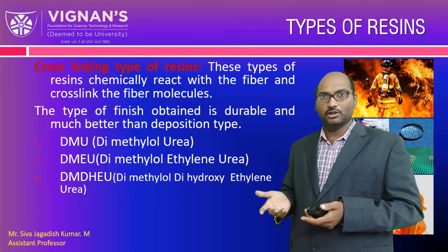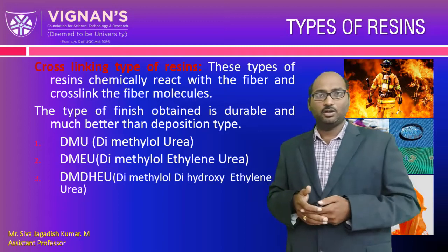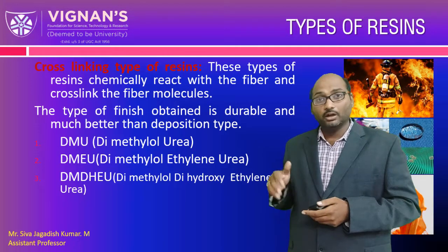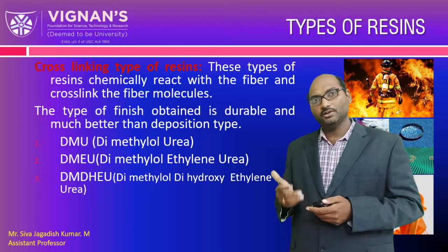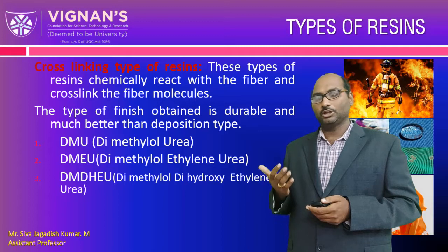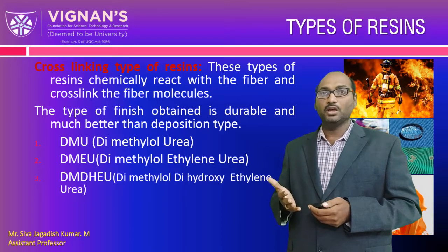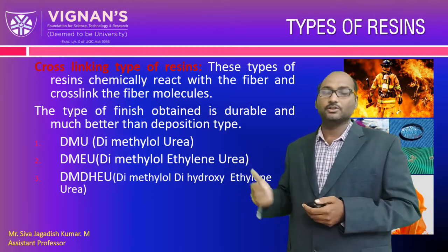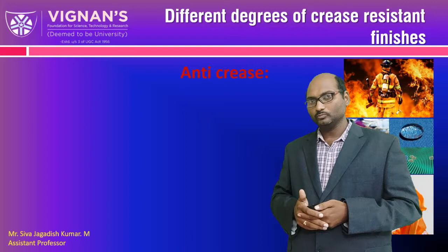As it does not react with water, obviously the hygroscopic nature will be down, so the water repellency will be increased. The resin finish will also improve water repellency, apart from making it wrinkle resistant. It can be used for both purposes.